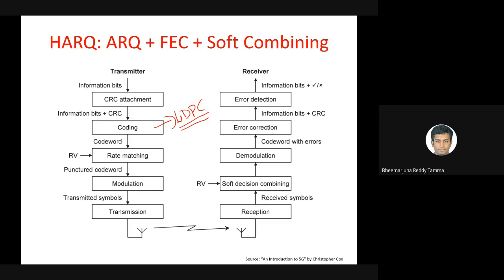So what you see is the coding. In some cases, the number of bits that are added, which are called redundancy bits or parity bits, could be 2-3 times higher than the original bits. Let's say if the size of the input is n, the output could be 2n or even 3n or 4n. That means, let's say you want to send 0, 0. Rather than sending 0, 0, if it is 2n, you are sending, let's say, 0, 1, 0, 1. So this is the original data.